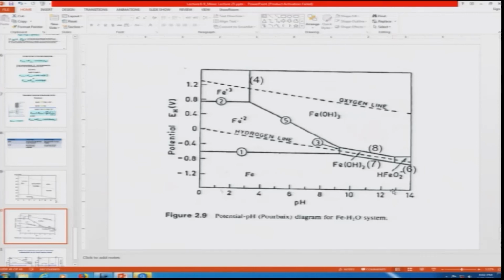At that high pH the iron passivates within the concrete system, when the rebar is placed in a concrete medium. So, if it passivates, dissolution becomes very limited at 12.5, but 12.5 is not suitable for aluminium, because at 12.5 we might get to the corrosion zone, which is AlO2 minus. So, this information we can definitely gather from the Pourbaix diagram.